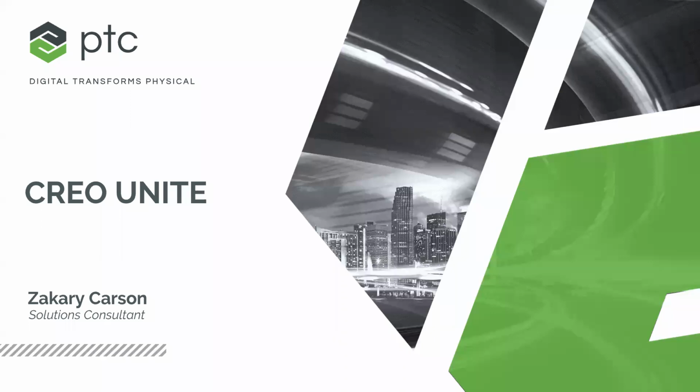Today, we're going to be looking at a capability within the base license of Creo called Unite Technology. And this started back with the release of Creo 3. What Unite Technology does is it allows you to import any or most CAD systems. So you can bring in a CAD file from Unigraphics, from SolidWorks, from Autodesk, and any of those types of CAD files, and even CATIA, and you can open them in Creo. So you don't need to have a third-party translator.